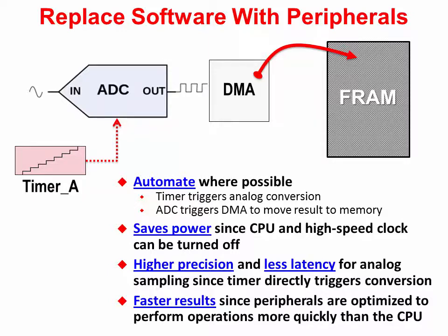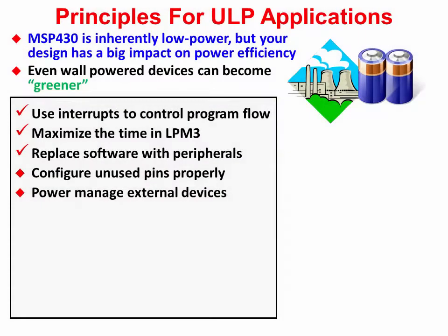and minimize latency. For example, when the CPU is used between the timer and the A to D converter, there is a small time delay while the CPU recognizes that the timer interrupt has occurred, and then it has to vector to the interrupt and begin executing the ISR. As small as this delay is, we can improve the determinism and minimize the latency by using direct connections wherever possible. Our next two suggestions: don't leave pins floating, and don't forget to turn off unneeded external system components.